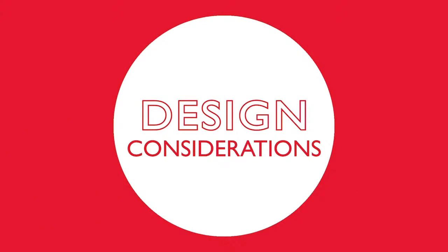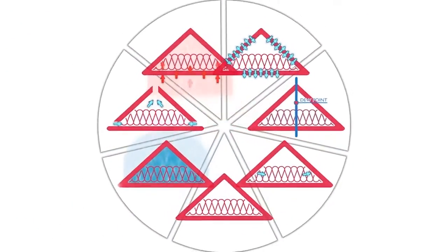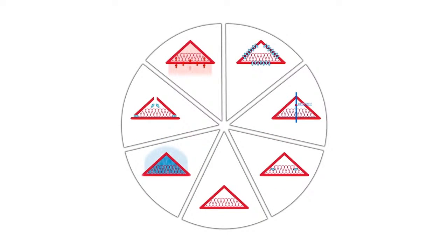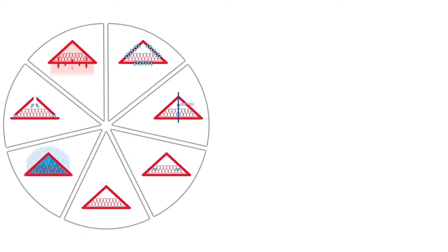The BS5250 standard gives detailed guidance specific to each combination of roof type and underlay type to ensure the response of the roof system to moisture is within acceptable limits. A roof that cannot adequately deal with moisture is susceptible to a variety of negative effects, from mould growth to structural damage and weakness. These prescriptive roof types have been developed based on a range of design criteria which must be balanced and managed. These constructions should not, however, be considered as interchangeable, as a variety of factors can influence the performance of the roof system.